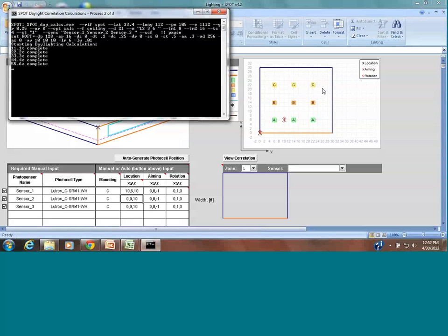So that's one way to save money and save complexity. The more zones you have and the more sensors you have, the controls become a problem, and you have to calibrate them periodically. So that's something that we've done in the past, is to just do one photocell and then control the other rows using an algorithm programmed in the lighting control system.